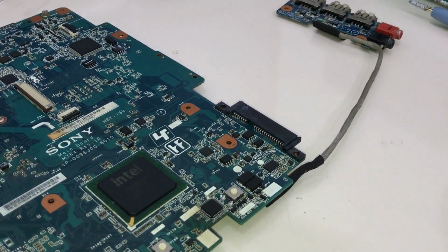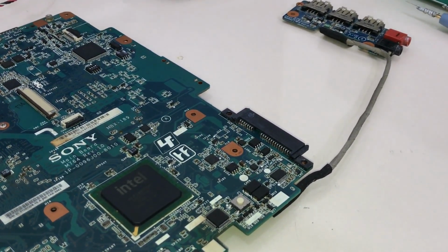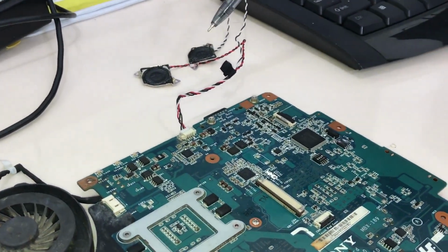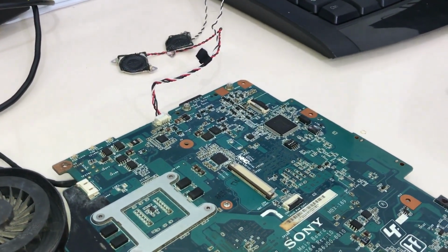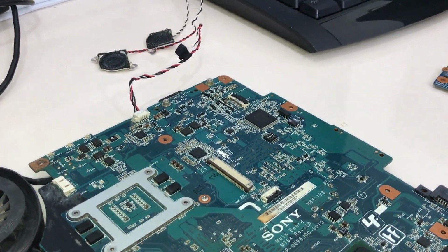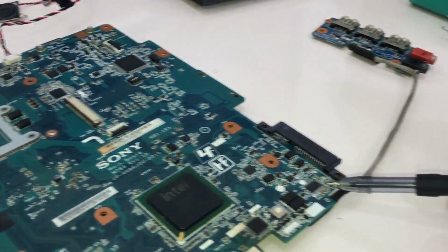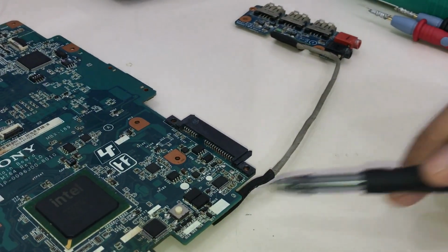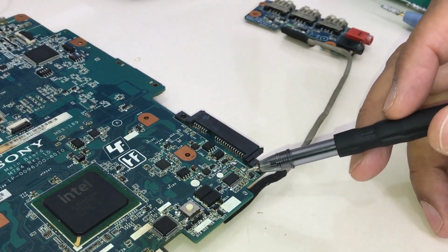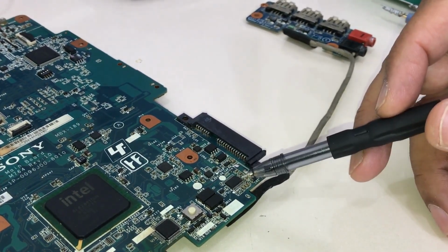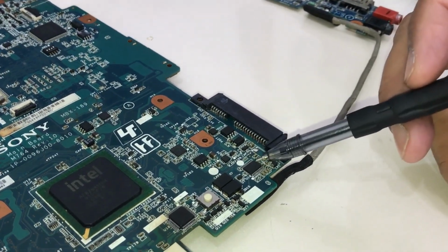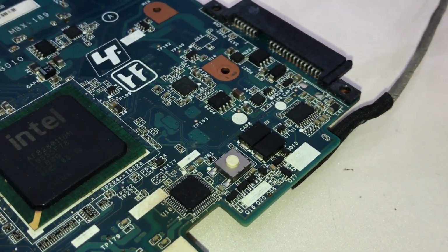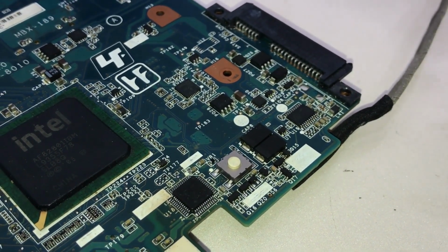In fact, there are 3 parts for troubleshooting the audio block. First, you should test the speaker. I recommend 2 ways to test speakers, besides the ways you know. Testing the amplifier IC signal, and testing the audio IC. As you know, each IC has power, input and output. I'll show you in the schematic as well. Meaning, if you want to know if an IC is okay or not, you need to test its power first, and then you should test its input and output signals.